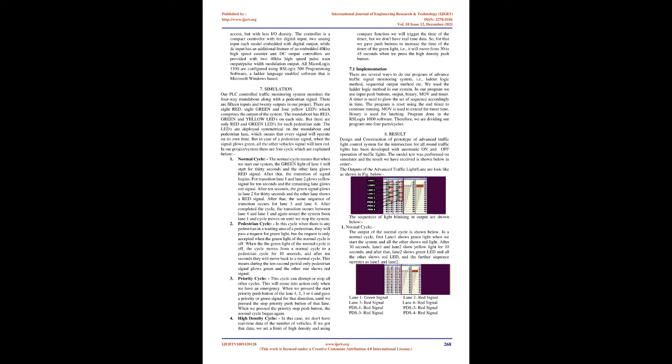5 Hardware. 5.1 Programmable Logic Controller, PLC. The PLC used is Allen Bradley. The PLC works on 24 volts direct current, and the sensors also require input and output of similar voltages. The PLC comprises both digital input/output and analog input/output. Digital inputs are 10, digital outputs are 10, analog inputs are 2, analog outputs are 2, but the requirement is 15 inputs and 20 outputs. To meet the requirement of the desired input/output, an SM1223 signal module is added to our project, which grants 3 more digital inputs and 8 more digital outputs.